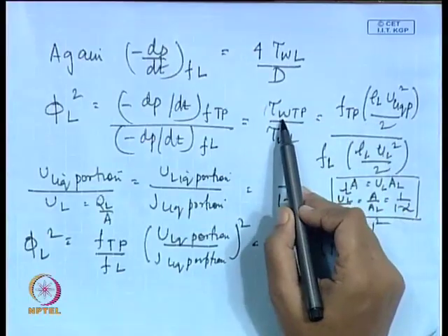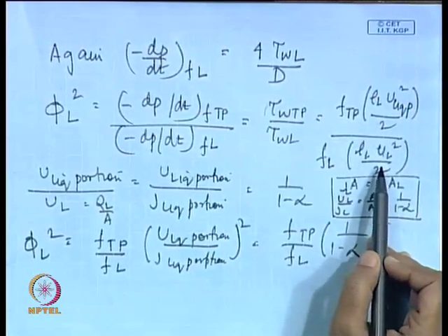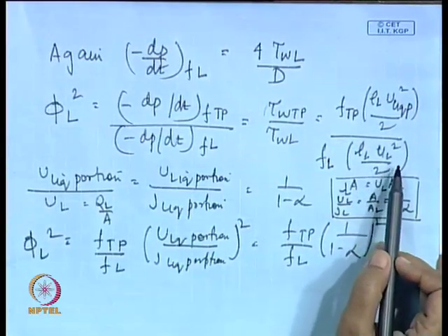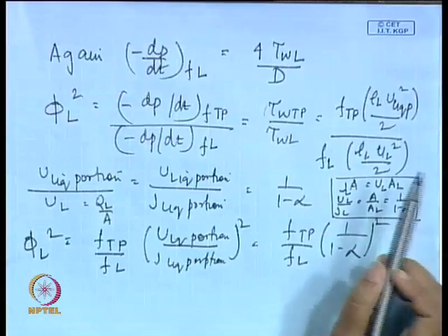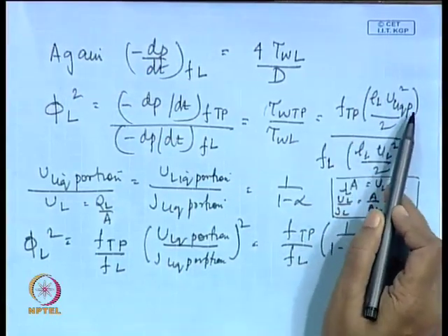If you see finding out your frictional pressure gradient or the wall shear stress, the expressions which you have used, you already know them from your single phase equations. Nothing new I am doing, but you have to keep in mind exactly what you are trying to do and use consistent things.